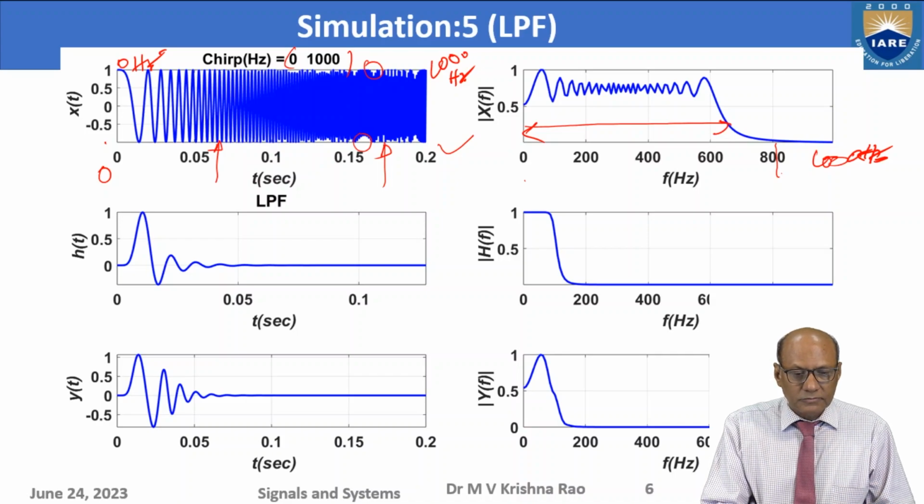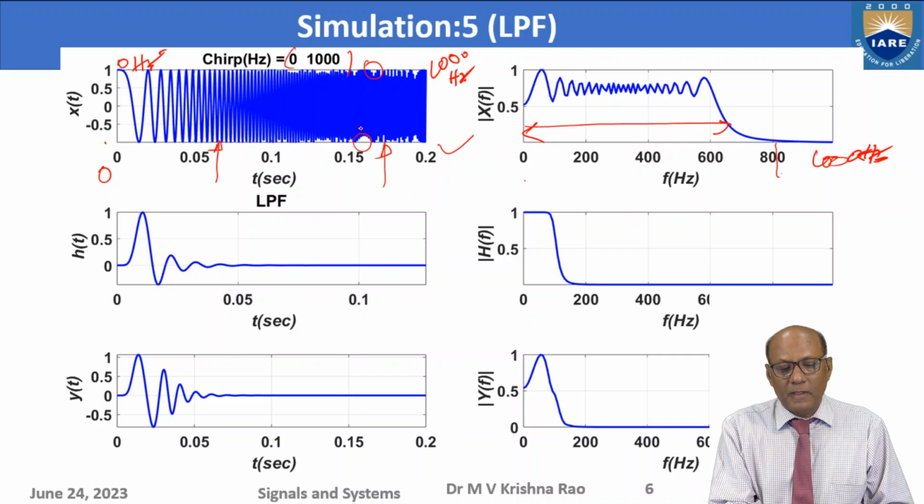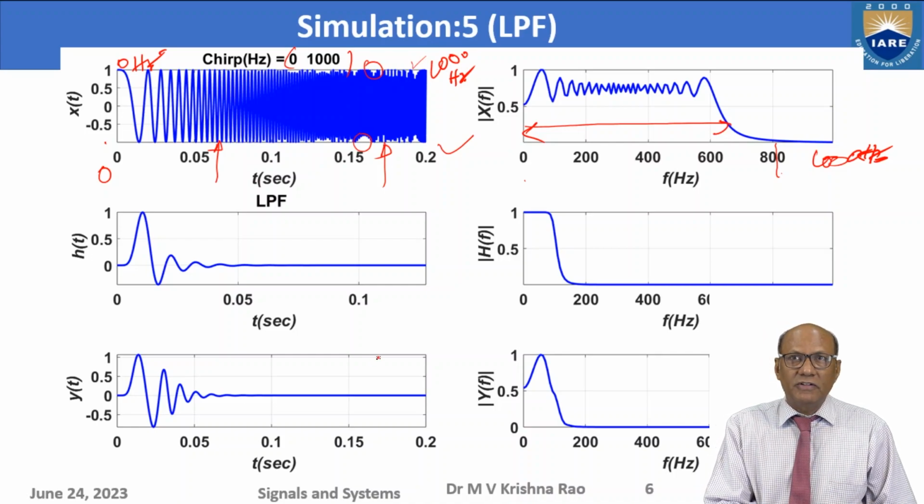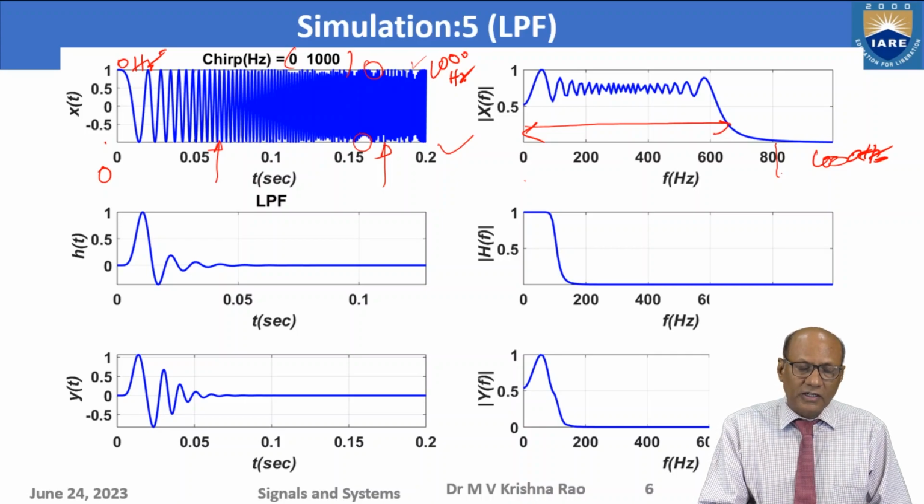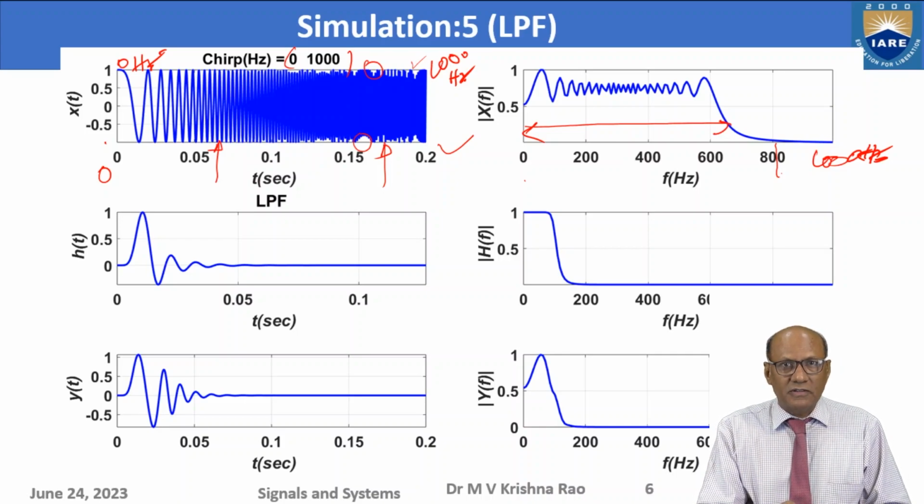In the simulations, if the frequency is high, the sampling frequency must be greater than the Nyquist rate. Let us say, for example, I take 1000 Hz. What is the sampling frequency I need? Minimum 2000. If I take 2000 Hz, I will get 2 samples per cycle: one during the positive cycle and one more sample during the negative cycle, if it is a sinusoid. It preserves the frequency, but you cannot see the shape. The time waveform appears highly distorted.